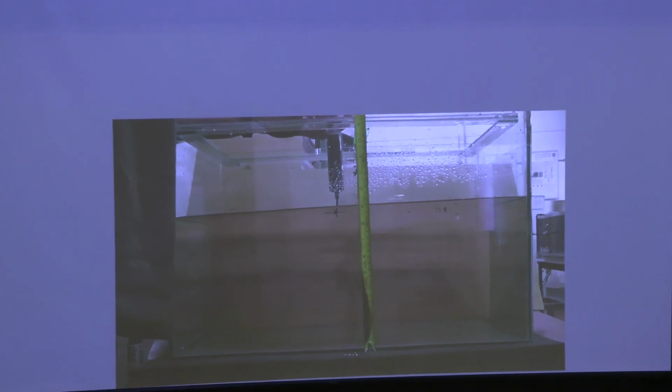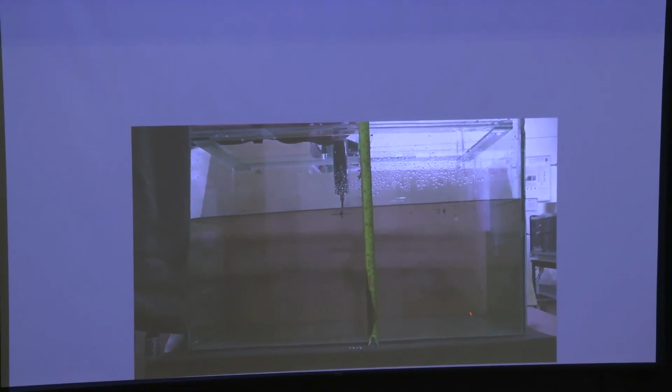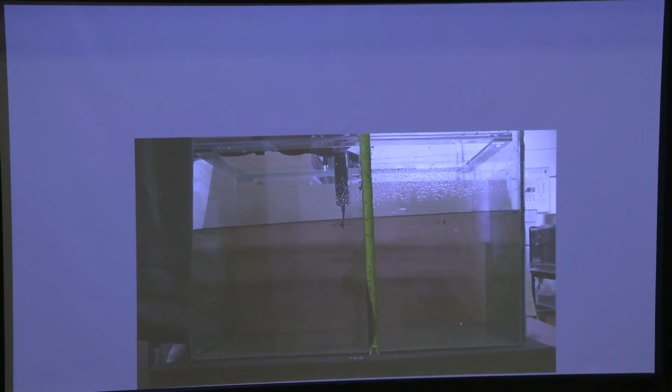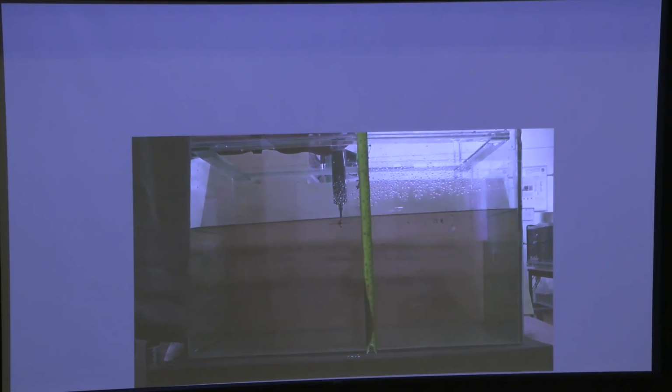Now, this is a really interesting question because it allows a very interesting simplification. So let me show you a little experiment. So this is a saltwater tank. Okay? So basically what we have is a tank of water, 1 meter by half a meter in depth. So basically the area is going to be 0.5 square meters. Okay? So if I take my ruler and I measure the height, I can have the volume of smoke. Okay? So if I inject a mixture of water and ink that makes this flow denser than the water, then the flow is going to come down, and it's basically an upside down version of injecting hot gases in cold air. Is that okay?